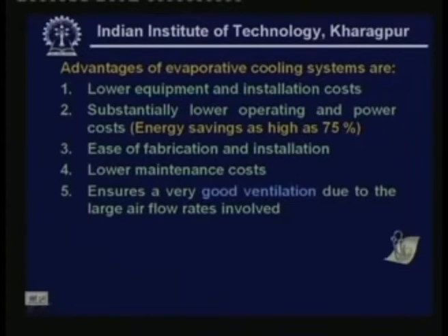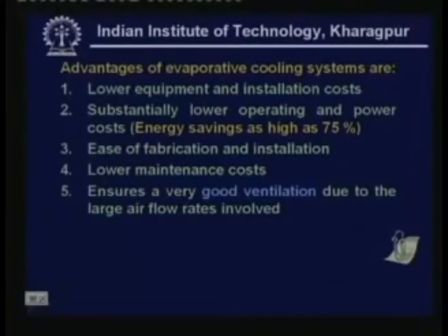And these systems ensure very good ventilation. This is because as I have already mentioned, the required air flow rates are very large in these systems, and typically in these systems you do not recirculate the air. Whereas in a conventional system you recirculate the air, in an evaporative system you exhaust the air. So you continuously draw fresh air, cool and humidify it and supply it to the conditioned space. Not much recirculation is used. Recirculation is not very effective also. So as a result, a continuous supply of large amount of fresh air is ensured whenever you are using an evaporative cooler. So this will take care of ventilation. Okay, so this is another major advantage.